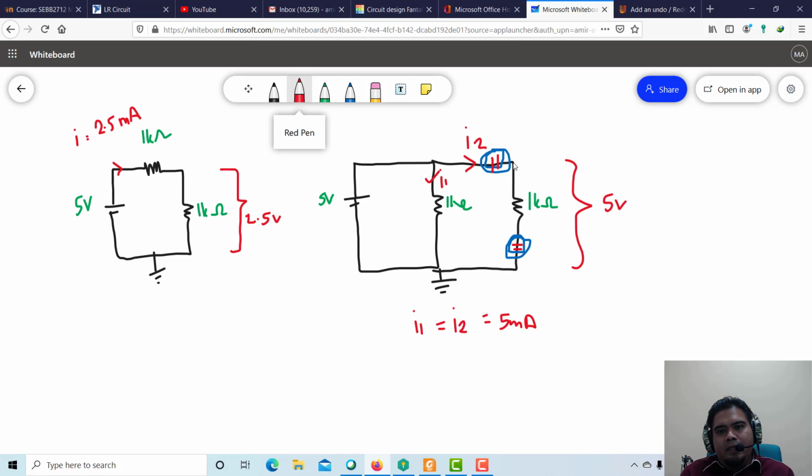So it's not connected together like in the normal circuit, where the connection is just one wire crossing over. But if you want to measure the current across here, you must cut that connection. This part connects to the positive terminal, and this part connects to the negative terminal of your multimeter. That's why in your simulation you must also do that.